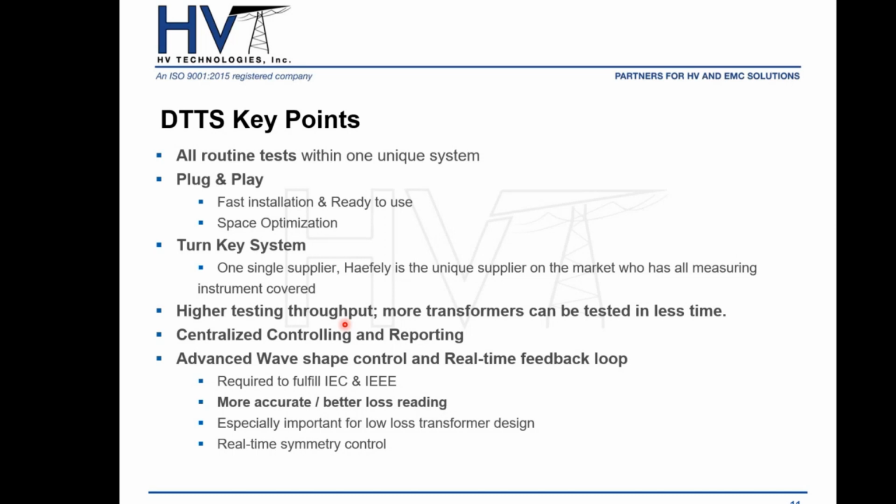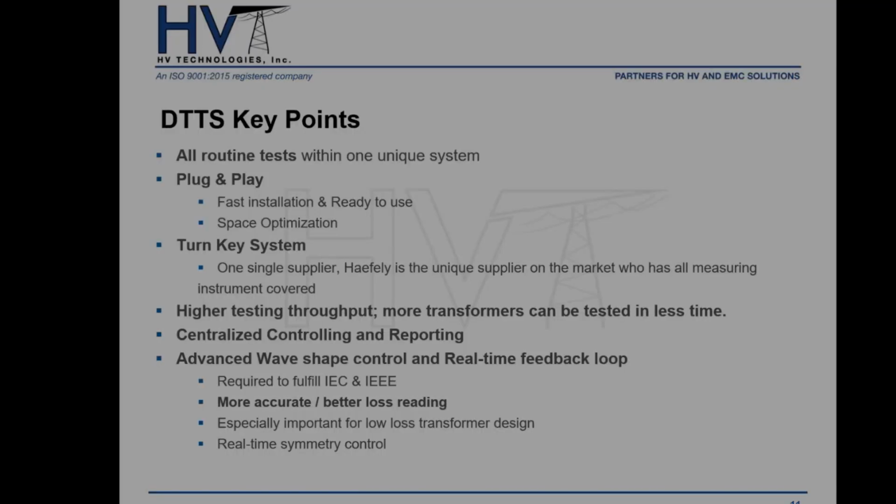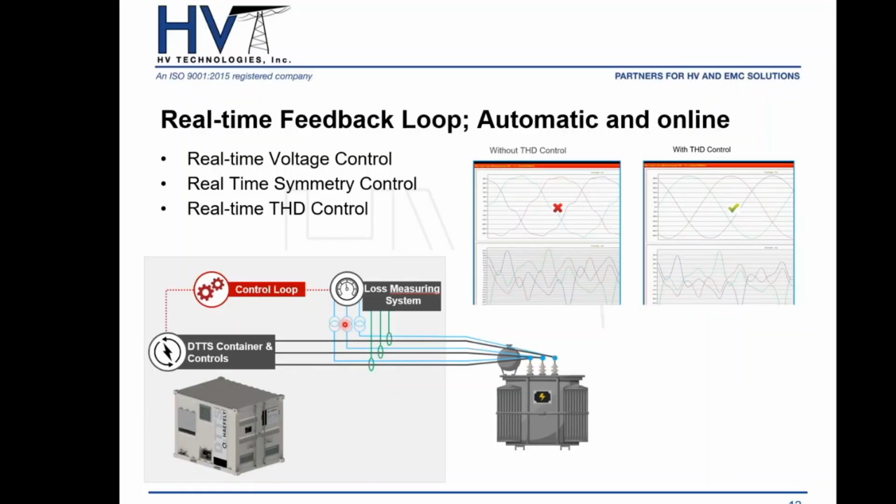So with this frequency converter, Haefely has been able to add a series of filters and other control technologies that will give you the advantage of being able to control wave shape and have real-time voltage control, real-time symmetry control, and real-time THD control.